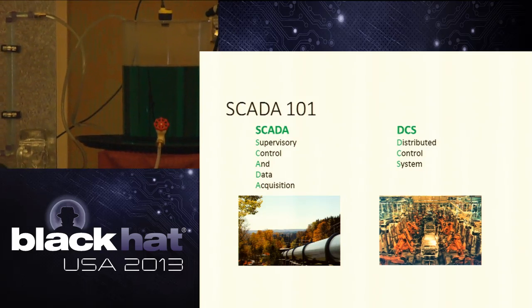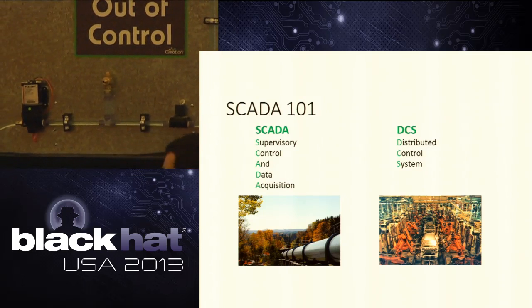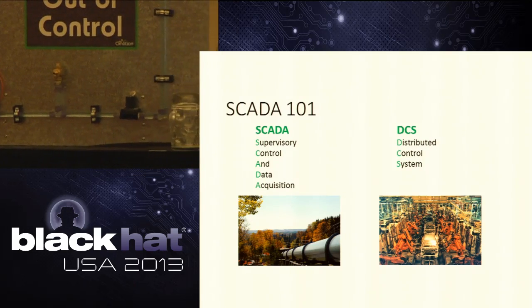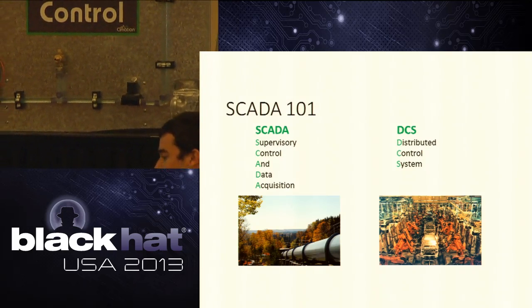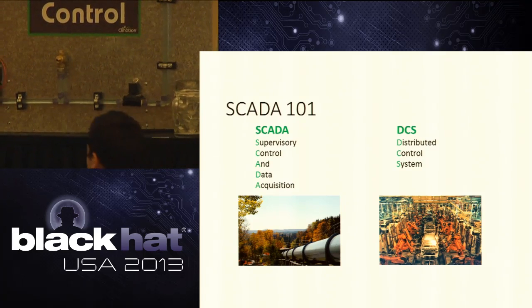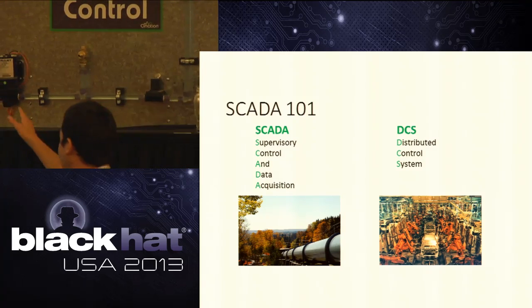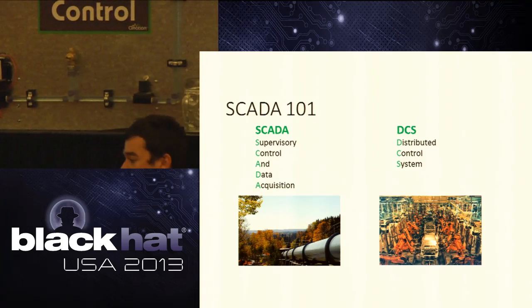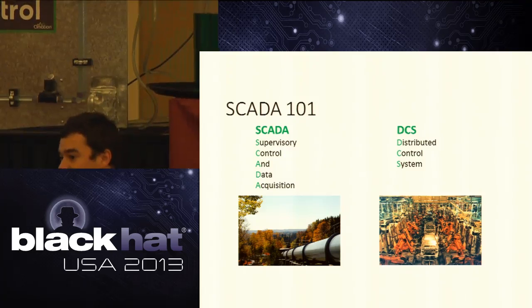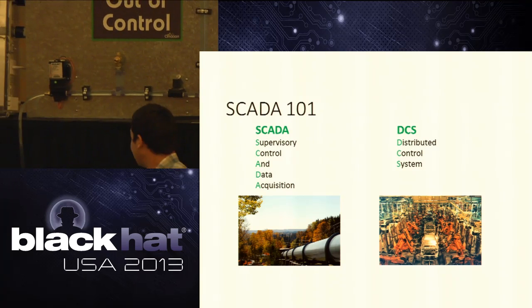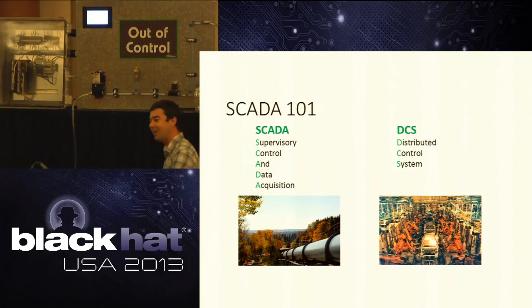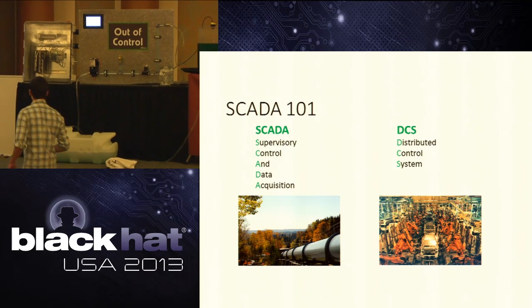One thing that we also have here is this little brass guy, and he's a pressure safety valve. You see those a lot in industry to prevent overpressures, but sometimes in production you'll have this pump and an isolation valve with no PSV in between. But we had to put one in just because we don't want to spray water everywhere. So we put one in for that.